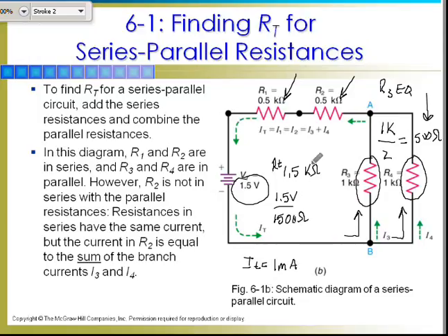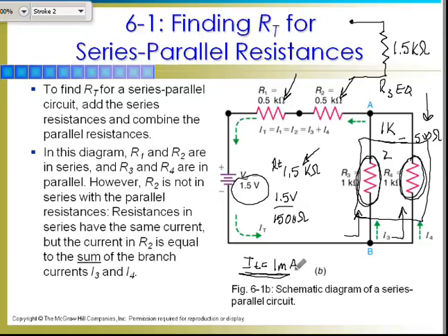So you see, I broke it down to simplest form. I determined what my equivalent resistance for this parallel bank was. Then I treated it like a straight series circuit, because that's what it becomes, to calculate what my total resistance was. So I expressed it down in the simplest form. And then I used Ohm's law to come up with my total current.